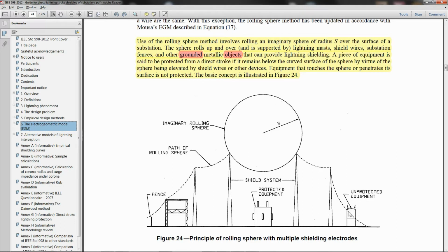Just to point out over here this breaker, which it says is unprotected, I would take that to be a live tank breaker, since if it was a dead tank and grounded, that arc should come down and make contact here at this corner, and then as it swivels back down here to the earth, the contact point should be tangent to the diameter of this circle.